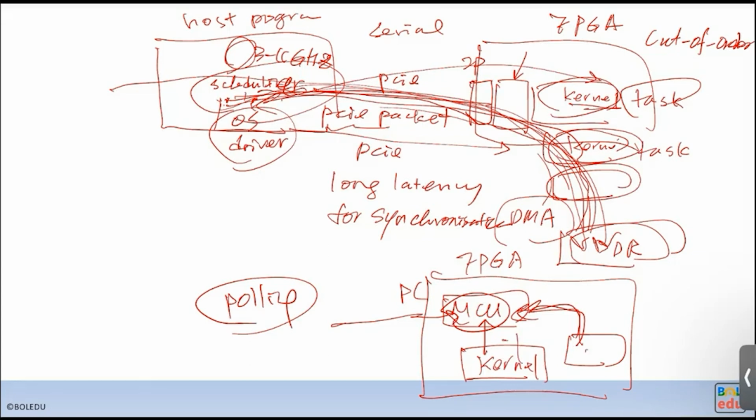Imagine there are multiple interrupt sources. When an interrupt happens, the interrupt handler has to poll each device to see which one gave the interrupt. So sometimes the code just does the polling, polling each device to get its status, and sometimes it runs faster in polling mode if this MCU is dedicated for that function.